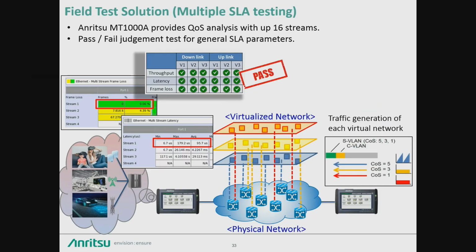From a tester's perspective, this is what it looks like. You basically have the tester that, as I mentioned, generates the eCPRI or radio over Ethernet traffic, each with the different service level agreements to simulate the applications. It treats it like a virtual radio, that's what our tester is doing. It's generating the traffic as if it was from the radio. And it's sending it through your NGFI 1, possibly NGFI 2, and then terminates that as if the tester is now the virtual MEC, or mobile edge. And we're testing it end to end, as if it's going from the radio to the edge.